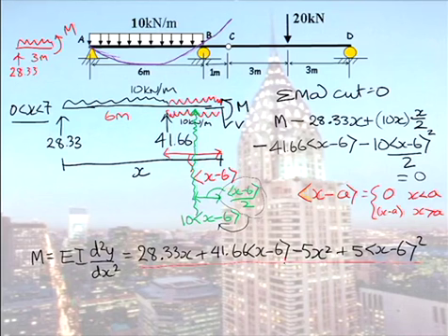And this final term would disappear as well. So the beauty of these equations is you can write an equation for a discontinuous system. Things just appear and disappear depending on whether you have cut them at that point. Okay, so we have our expression for our bending moment, and now we know our deflection is equal to the second integral of m on EI.